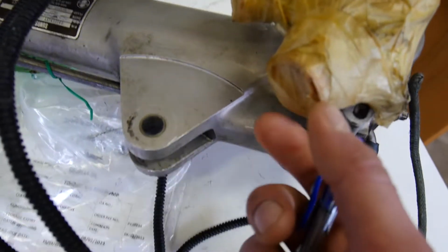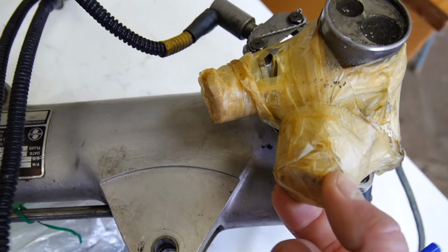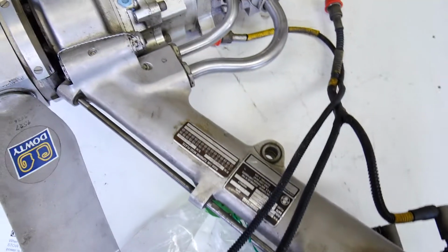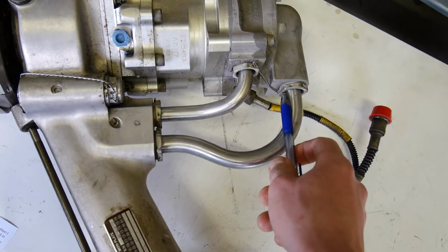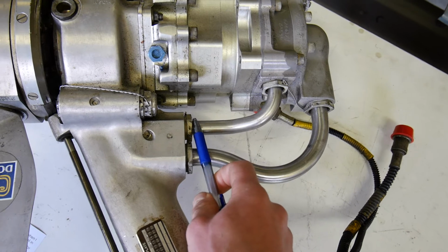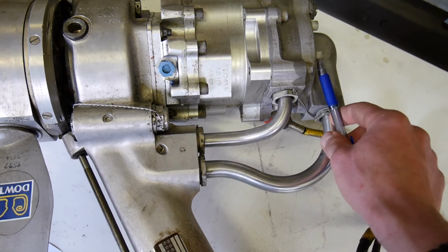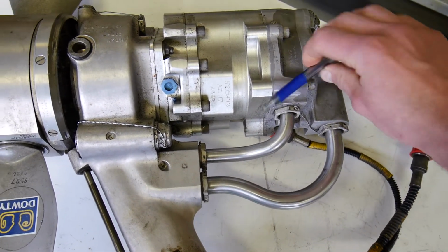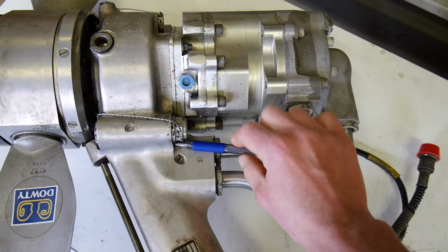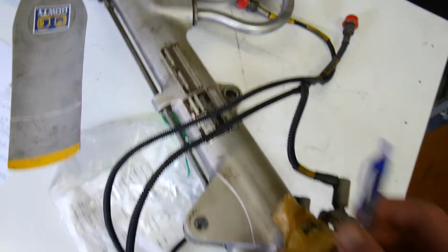And these two pipelines escape from here. Here are the covers, we can remove them, and you will see two pipelines. The larger pipeline is the supply, and the smaller is the pressurized line. From here we get hydraulic power from the airplane, then the pressure rises, and under high pressure, hydraulic fluid is supplied back to the airplane.